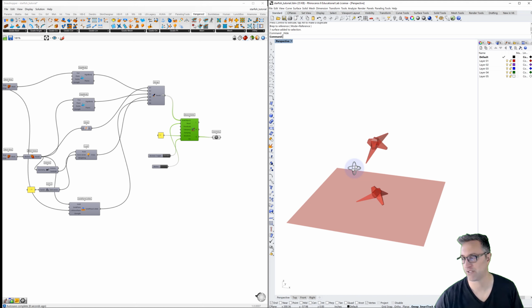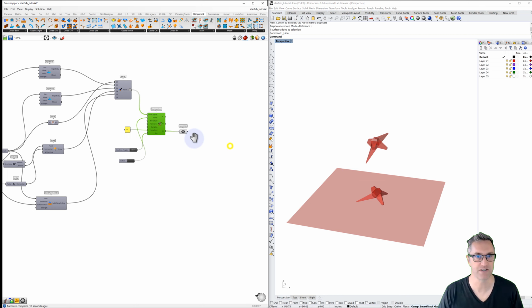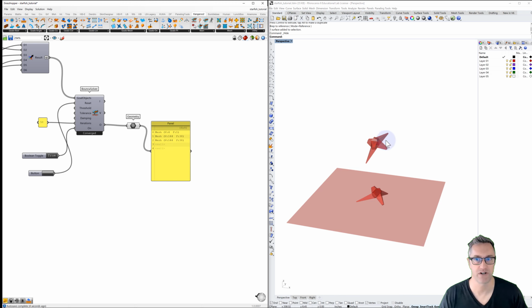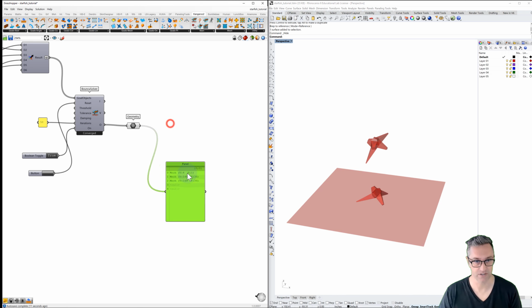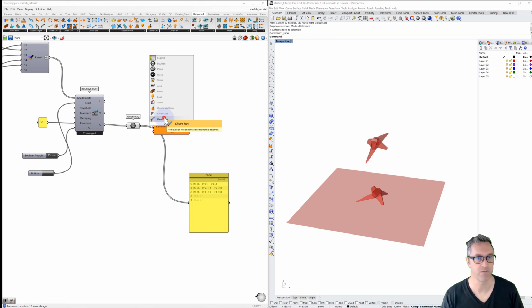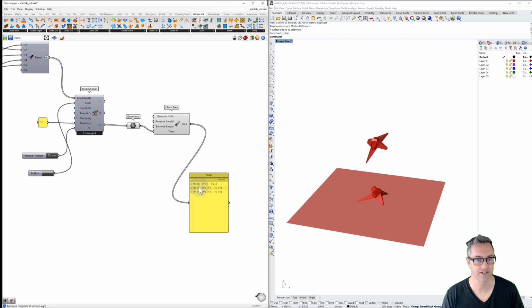And what I want to do is to play with the representation a little bit. Because with this geometry, if I create a panel, we usually have a few different things. We can see we have our starting mesh, our ending mesh, and our planar mesh, and then 2 nulls. So first thing, I'm going to keep the panel here. Let's clean our tree because those nulls can create some problems for us. So let's just plug this into our tree. Let's look at this now. So now we've removed the two nulls.